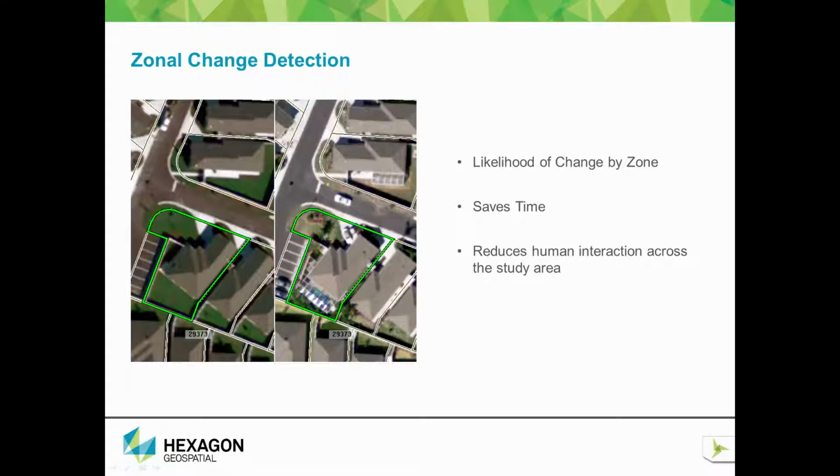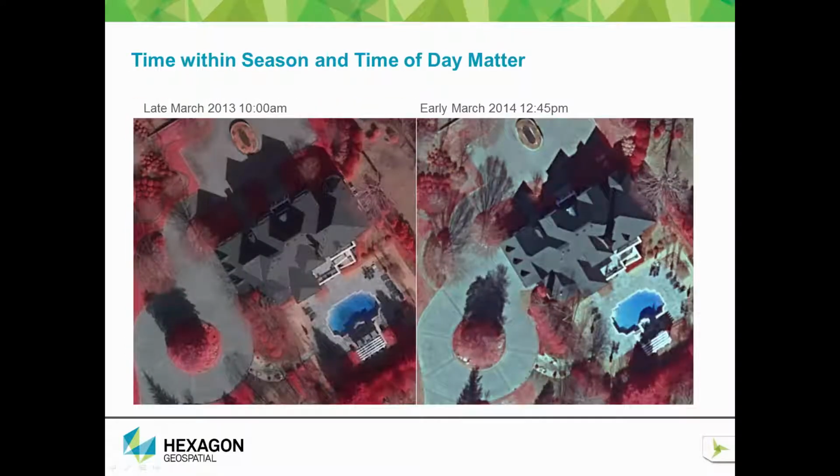Always remember that the results of any digital image change detection process are largely determined by the quality of geographic correction and overall image quality. Always use two images that have the most similar characteristics as possible. This includes the season, time of day, and atmospheric and ground conditions when the imagery was captured. In addition, the images should have similar spatial, spectral, and radiometric resolution.